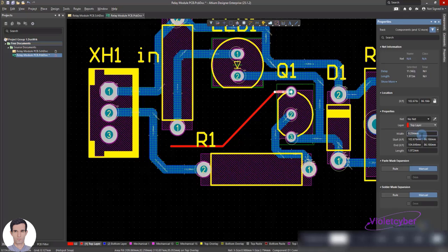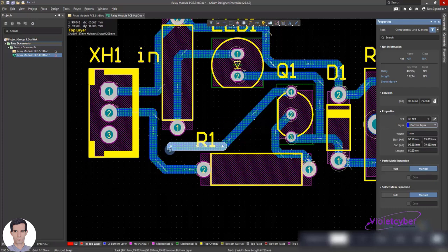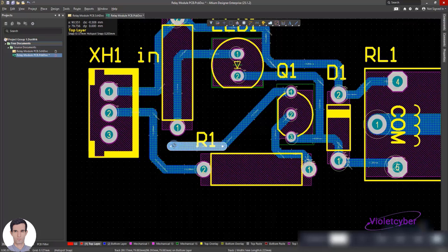If we come to put these legs on the bottom layer like we do, so far it's okay and right. The other legs should be, like the other paths, inside the layer. But we don't know the inside of the layer, so let's pass through here. Now Altium itself may not allow it, a short connection will be created, where these two parts are connected together. But the negative side of the transistor, or emitter, is not supposed to be connected to the signal line. So what do we do here?